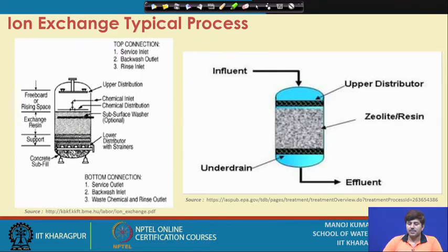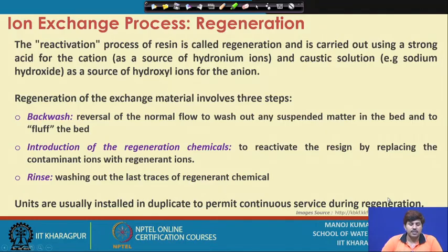What typically happens is that there will be resin here, the influent will be passed in from the top, distributed through the resin, and collected through an under drainage system and passed on. That is the basic process, and in and around it we can put in other different mechanisms to deal with that.